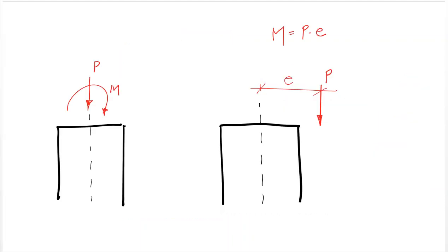If you look at a particular cross-section, what you find is that when you have axial P and bending M, that can be made equivalent by simple statics to an axial load acting eccentric with respect to the centroid of the cross-section, and we call that the eccentricity. We can simply find it by dividing the moment by the axial load, and we get the eccentricity.